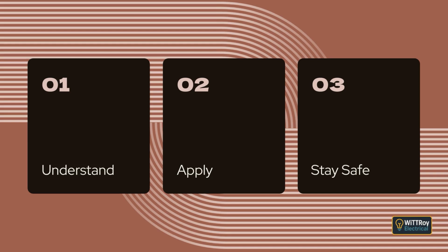Clause 2.5.1.3 Omission of protective device for safety reasons. This clause explains when a protective device may not be installed. If opening a circuit unexpectedly could create a dangerous situation, then overcurrent protection may be intentionally omitted. This applies to certain safety systems, lifting magnets, emergency supplies, or control circuits that must never lose power suddenly.